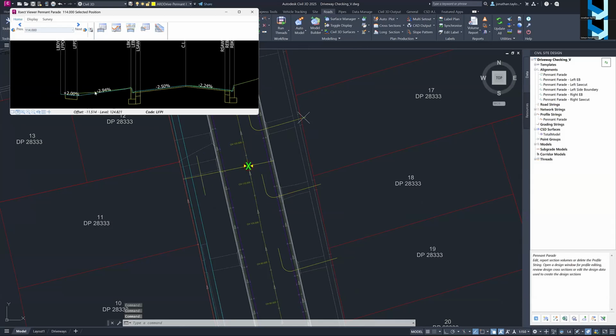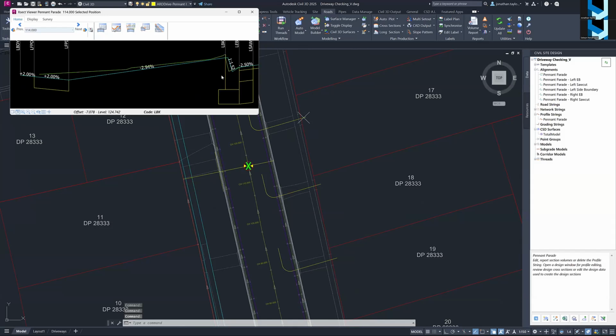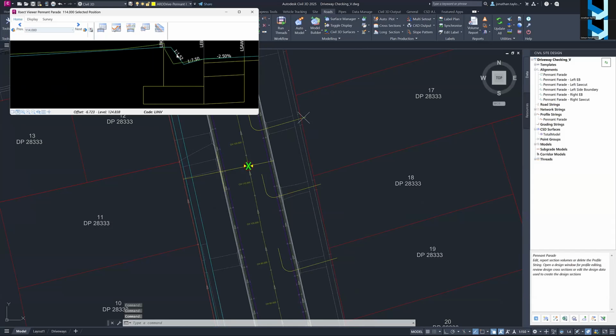If we just open up a cross section here, we're actually going straight down back towards the boundary. And then hypothetically we're putting a footpath in, which is obviously going to create some kind of issue with drainage potentially, but at the moment, that's just what we're being presented with, and that's what we want to check. And obviously what we also want to check is if we were to remove this part of our curb and put a layback in, how would it perform?